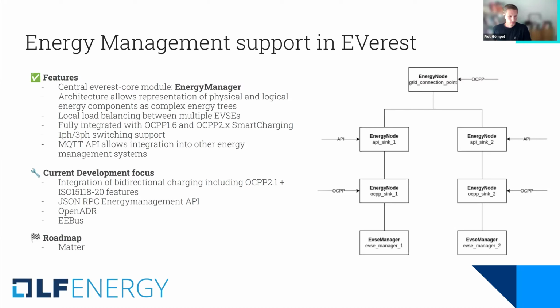We plan to implement other features of the energy management in the future. As you can see here below, the current development focus is to integrate OCPP 2.1 with lots of requirements, and all the requirements that come with ISO 15118-20. By the way, the requirements from OCPP 1.6 and 2.x, like 2.0.1 or 2.1, are implemented as part of libOCPP and the OCPP module.